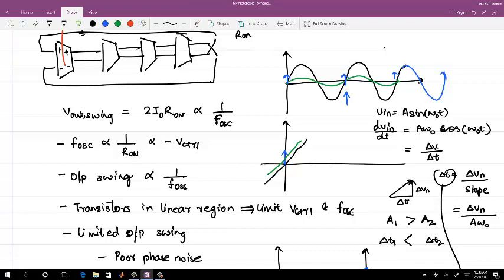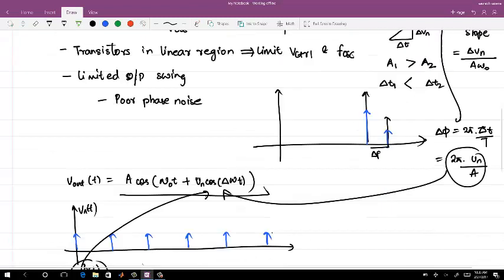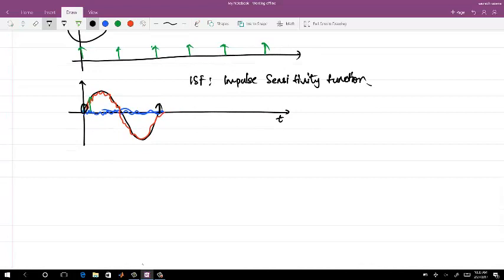I mean, power consumption in any digital logic is dependent on the amplitude and your oscillation frequency, right? So this is opposite. As the oscillation frequency goes up, your amplitude goes down. So any of the capacitors which are charged and discharged at every oscillation frequency, now they are charged and discharged to a lower amplitude. So power consumption is not directly proportional to the F oscillation in this case. But that is not the requirement. That is somehow the drawback here. Okay. So any questions on this?